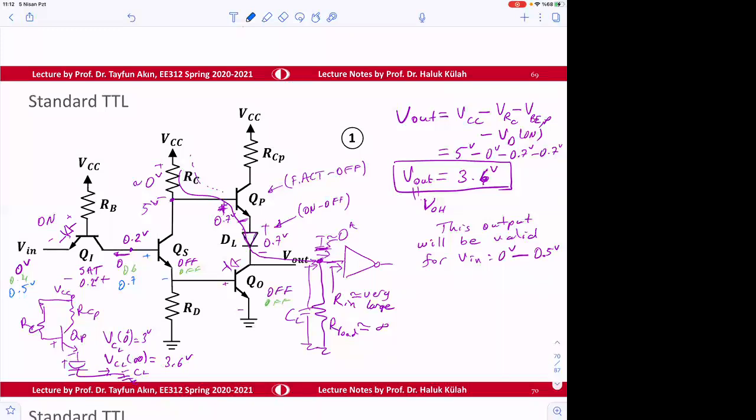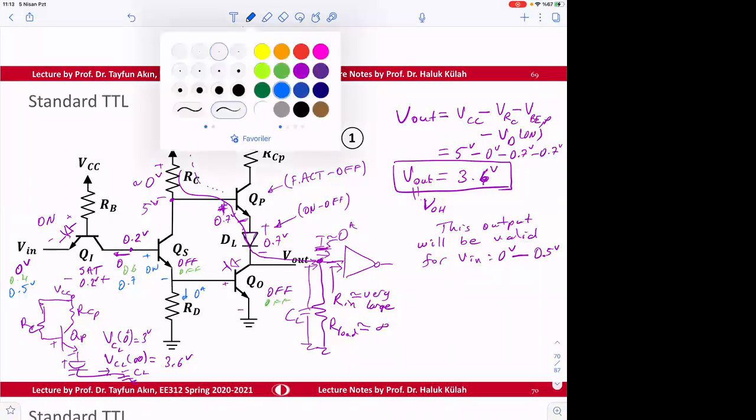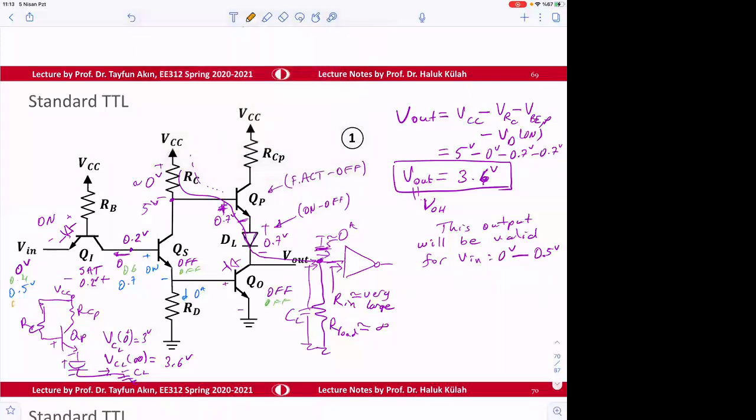And that 0.7 volt starts turning this on, becomes on, but still the current is 0, because that's the edge, okay? 0 amp. But when this becomes, let's say, 0.6, this becomes 0.8, this remains 0.7, and then you will have 0.1 volt here.